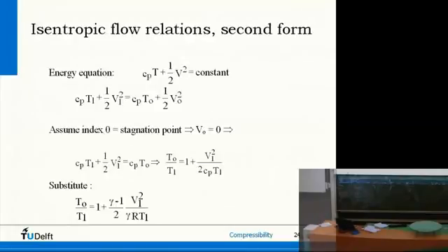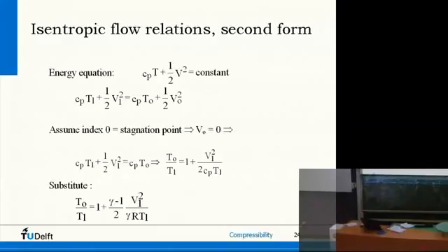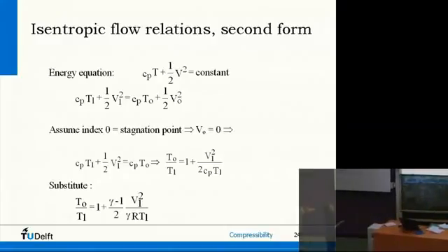So this Cp here, I'm going to replace by gamma R divided by gamma minus 1. But of course I have to divide over it, so the gamma R turns up here, gamma minus 1 there. So reworking this pressure specific heat coefficient, I get to this version. And now see, here's my A squared, right? My A1 squared. So I have V1 squared over A1 squared, so Mach number squared.